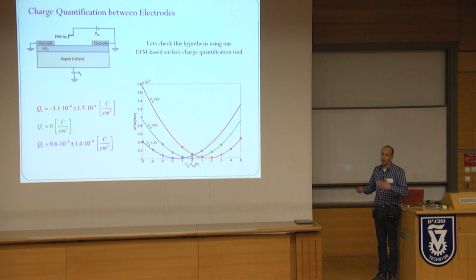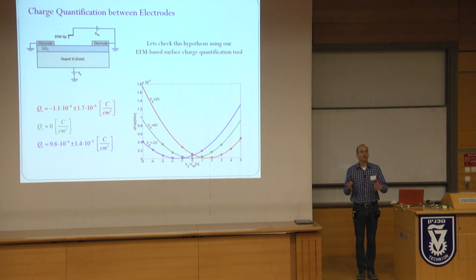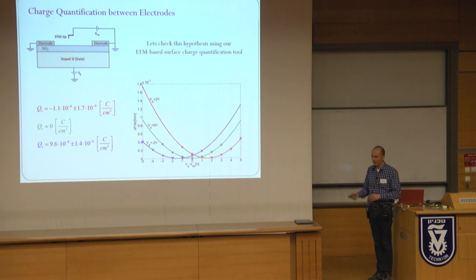Because if you think about it, if the same thing happens with a suspended nanotube and an on-surface nanotube, and the water is not on the carbon nanotube, it cannot be that electrons leave the carbon nanotube and cause this hysteresis behavior, because the carbon nanotube is suspended. It cannot tunnel from the nanotube in air to the surface. So we just need to study this charge.